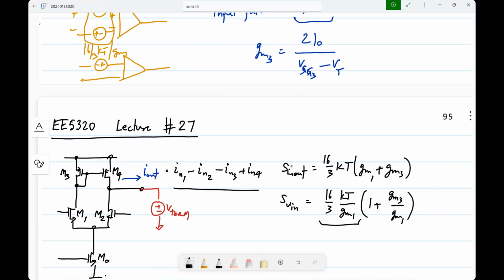So typically, whenever we are discussing trade-offs and changing some parameter, it is assumed that you are not changing everything else. The op amp has some unity gain frequency. You can't change that because you want to change the noise, because that's a primary specification. The idea is you keep all those things fixed and then you change this. Usually, if you can find a hook like that in any design, that is, your design is working except for one parameter, and you find a hook that influences only that, that will be good. But actually, this is usually not the case.